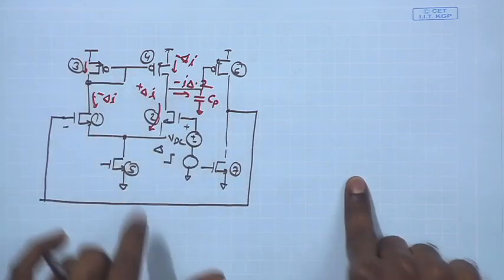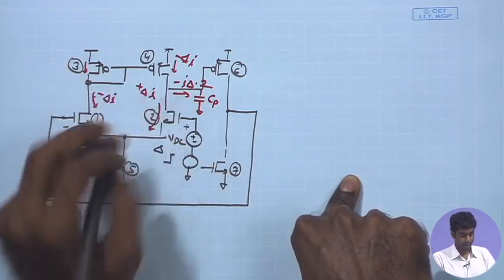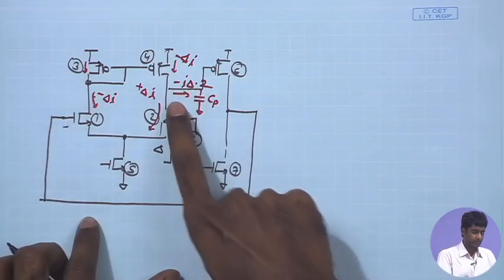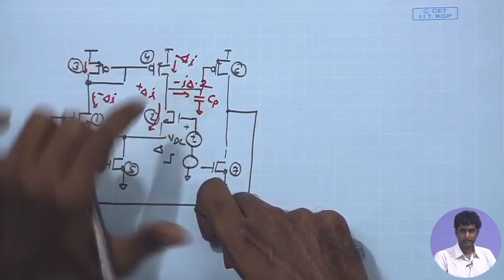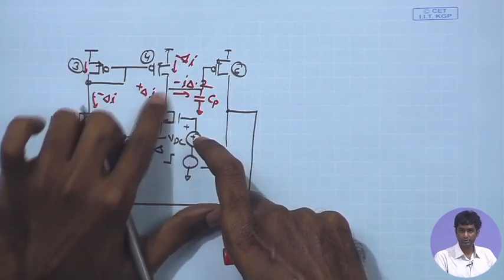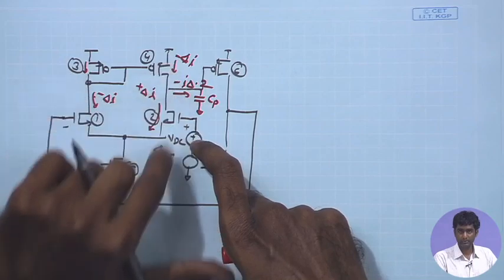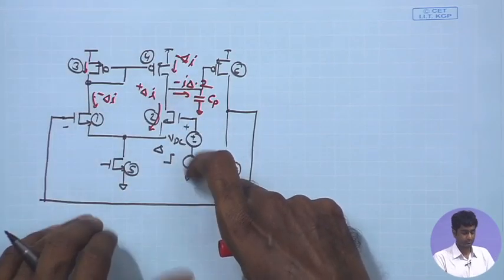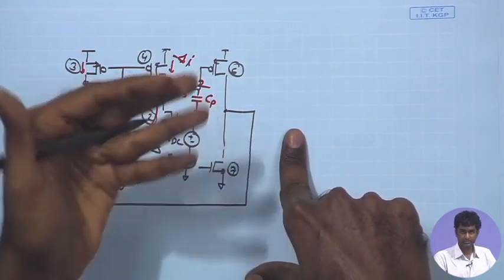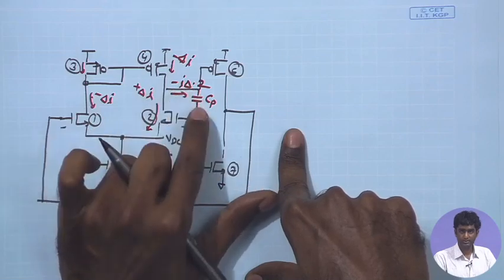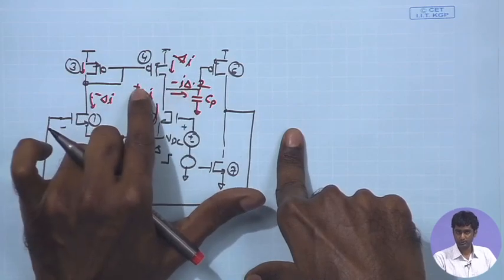And if I assume that you have the small signal resistances also, of course, they will be also contributing to some of that current. So, here I am not talking about the RO of the PMOS and the NMOS. In the usual analysis, you also have the small signal current paths, the ROs of the NMOS and PMOS. So, they will also be contributing to the KCL equation, but if I just look at the capacitor and see what is its behavior, so ultimately when this node is supposed to charge, this parasitic capacitance is going to increase or decrease depending upon the direction of the net current flow.